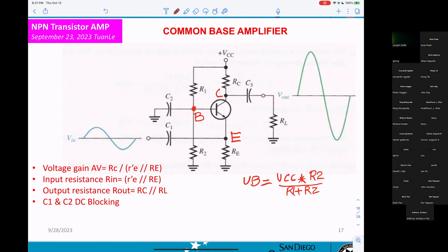Hey, Mr. Pham, you asked for the name of what? C2. Oh, C2, you mean like the coupling capacitor? DC blocking? Okay. DC blocking, AC coupling. Coupling. Okay. Now, why do we need that C2 in this position? Who can explain to me? You don't want the AC signal to go to ground. Well, common base amplifiers are common to the ground, so that's how you connect the base to the ground, and you have to have the coupler. Okay, common base, AC they will be grounded. Correct?